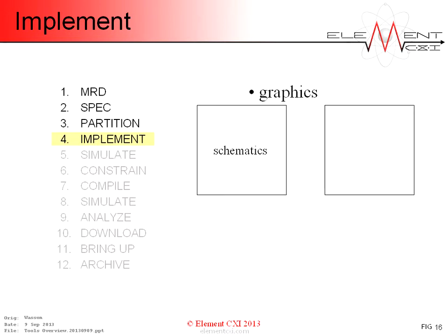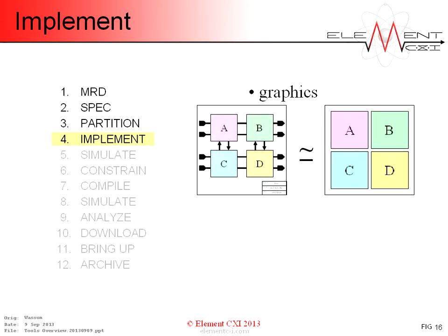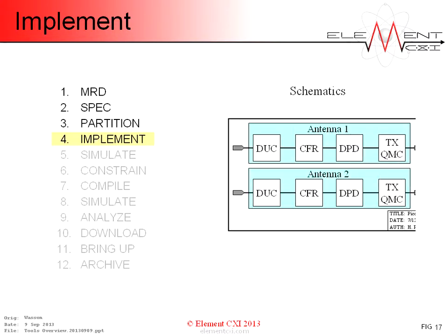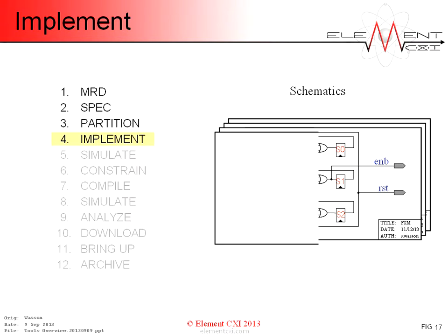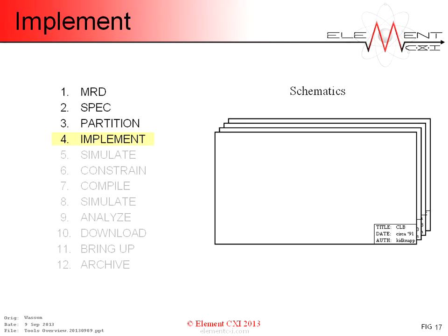Graphic-based tools have the advantage of topological similarity, which enables significant area and performance efficiencies. CXI's ECA is particularly amenable to graphics-based implementations because of the architecture's medium granularity and hierarchical regions. Schematics and block diagrams are superior for data flow implementation, but they are less efficient at defining control logic. Schematics do offer partitioning constructs not readily available in HDLs. Here's a Xilinx configurable logic block primitive.